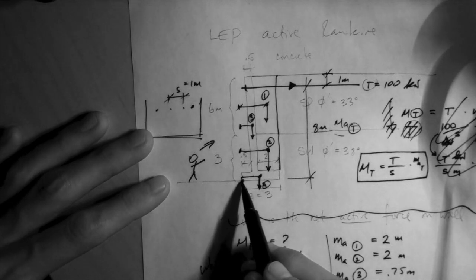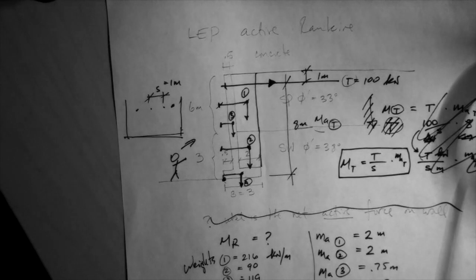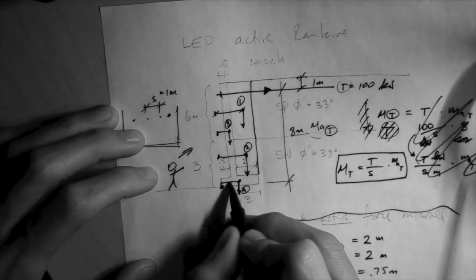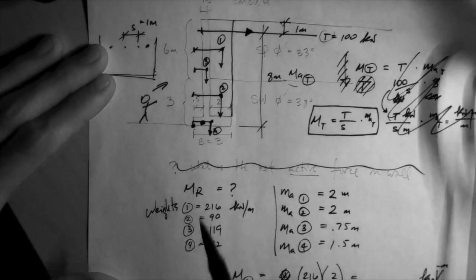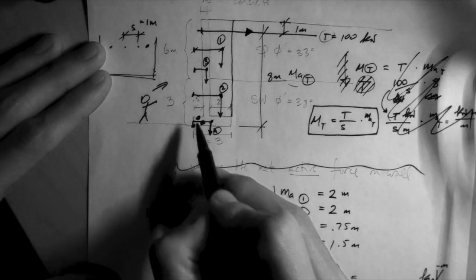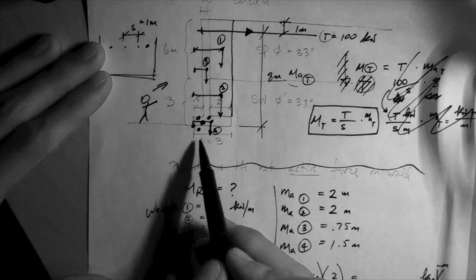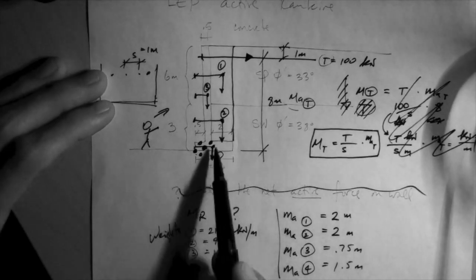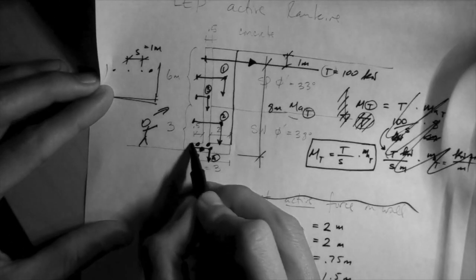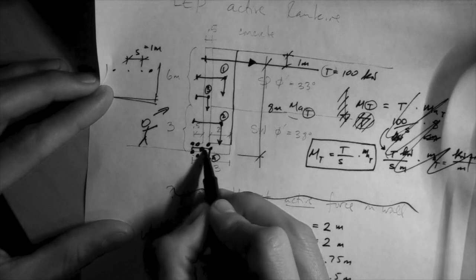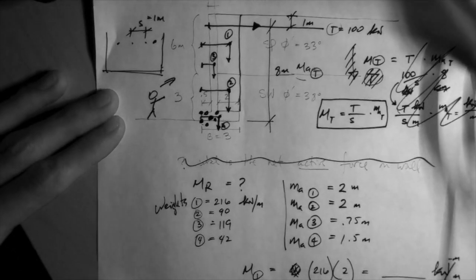That point is the one that was selected for our analysis. So you would say, okay, that's my factor of safety for that point. Now let me put the point maybe around here, and run the analysis again and get the factor of safety for that point. And maybe a point down here, maybe around here, maybe here, right? Locate it around here because that's where the system is likely to rotate. The lowest factor of safety you get is the actual answer for the problem. It may be for a point down here, and it may very well be the corner point that we selected initially.